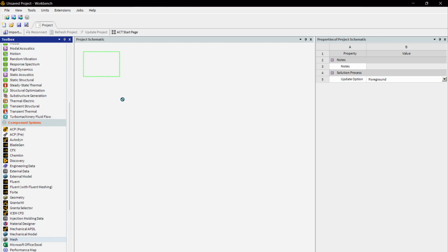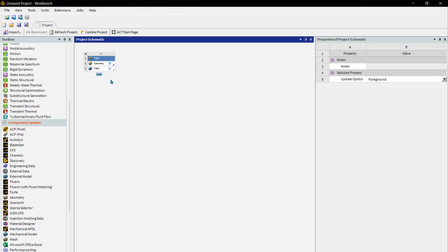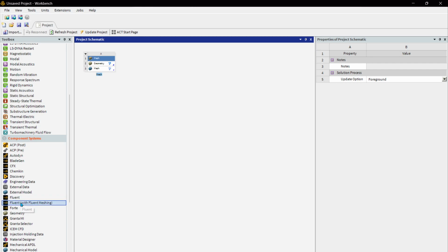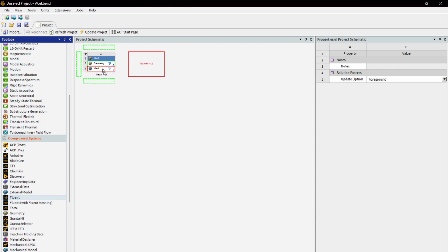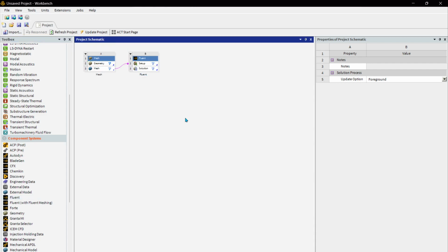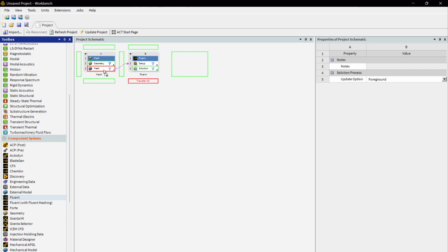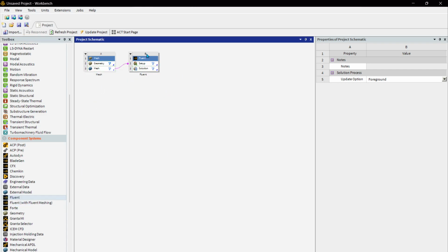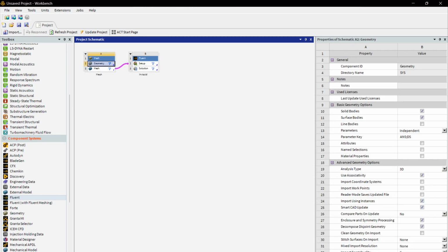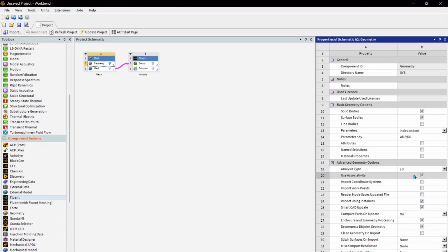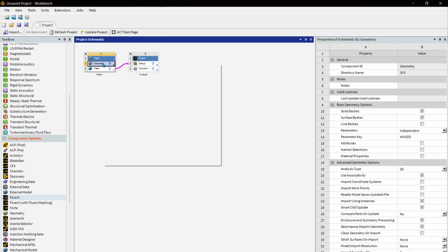So to start with, we will put a mesh in here, and then we will go to Fluent, not Fluent with Meshing, just Fluent, and connect that with the mesh. There you go. Setting it up like this, we could also set up the other cases, just sharing it as well. But for now, we're going to start with the inviscid flow. All right. Be sure to set this as 2D and then open it.